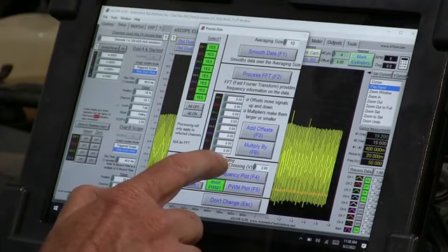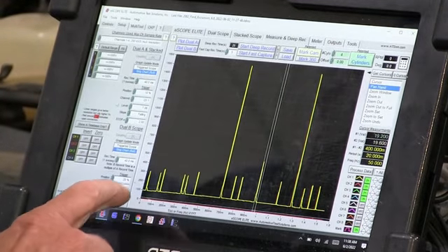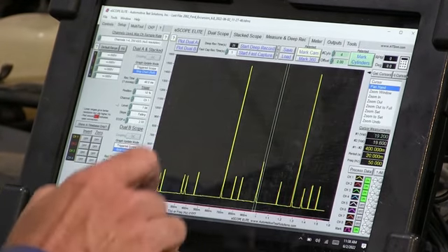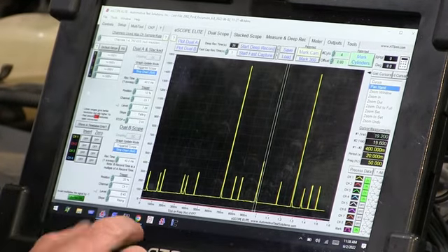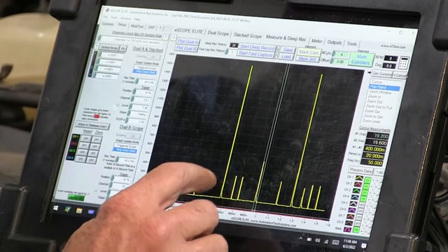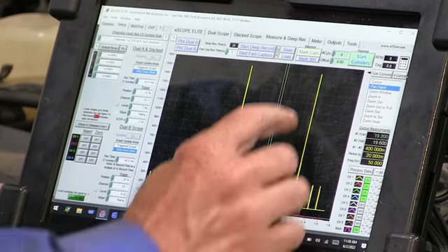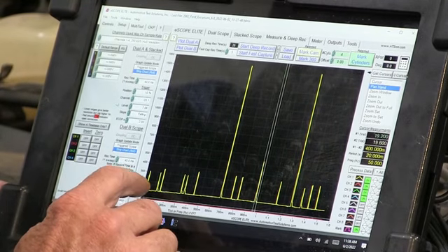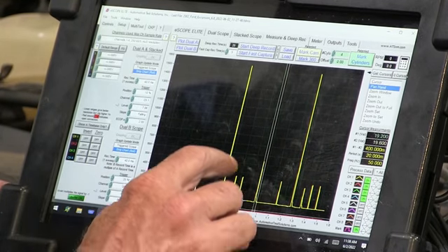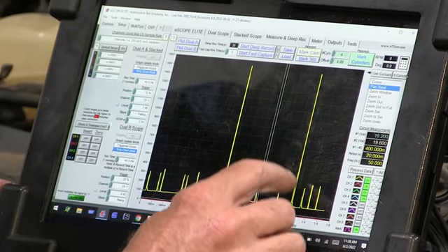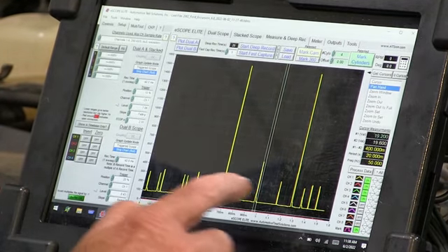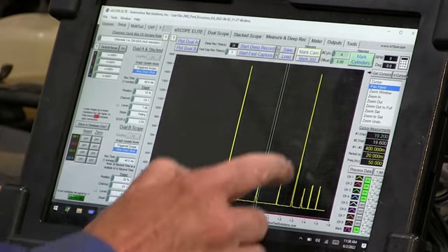Gonna run the frequency plot on this. Look at the frequency plots. Every one of these is changing the frequency, and you see how it's jumping the frequency all the way up? Well, this is my shaft speed down here with where these spikes from the ignition are hitting, and we can see how high it's getting here. So that's definitely, the computer's going to see that.